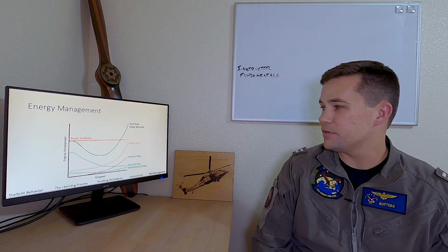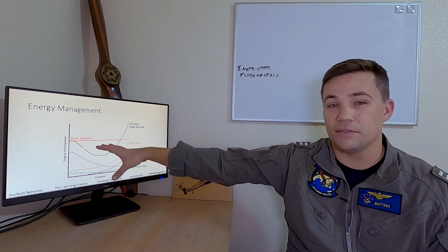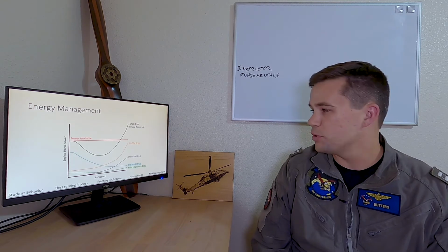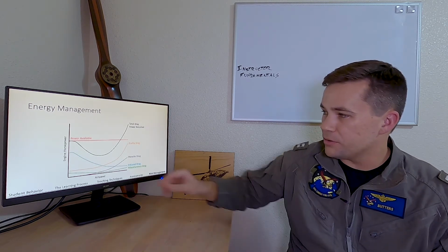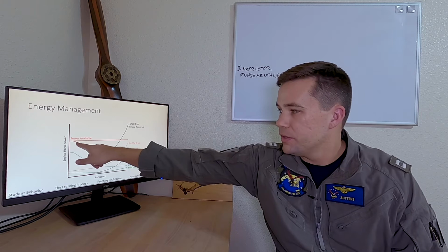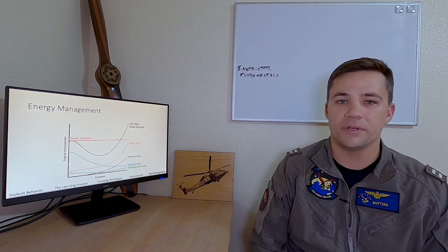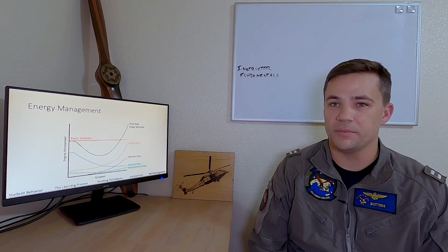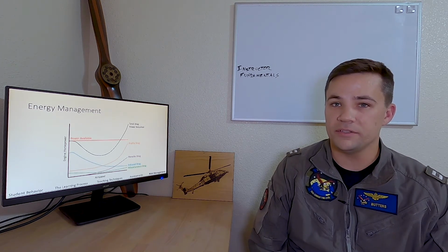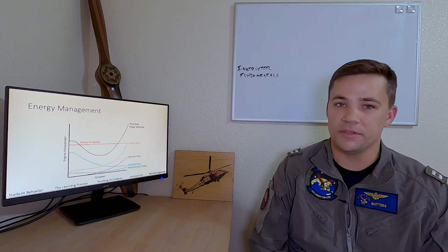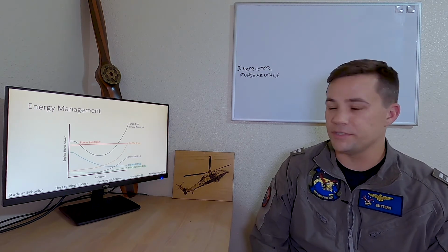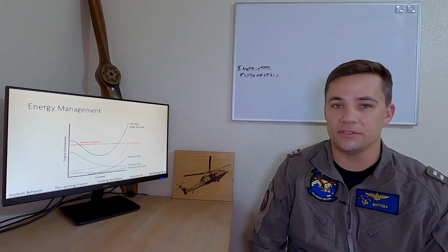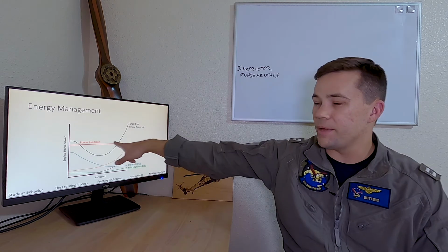And this presents us with a situation that's pretty tight, right? This is definitely some place where you'd want to do a running takeoff and landing, or at least a max gross profile. But it also, as you can see, is where you start to get into these areas where the amount of energy you're able to add to the aircraft becomes very small, and this is where you can really get into some risky business. You find yourself in a situation at a higher density altitude, higher gross weight, where this is your max power available.